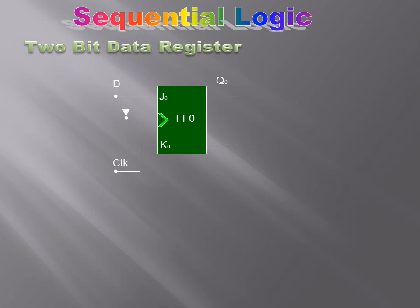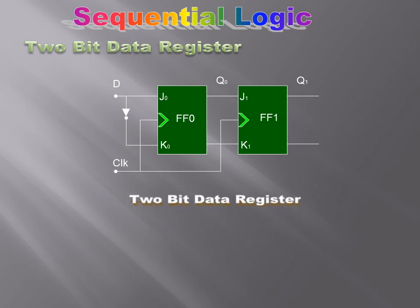So if a D flip-flop is there and we have 1 or 0 at its input, the flip-flop will store whatever the value of D is. If such flip-flops are connected in series like this, it forms a 2-bit register. A single flip-flop is a 1-bit register, and 2 flip-flops is a 2-bit data register.